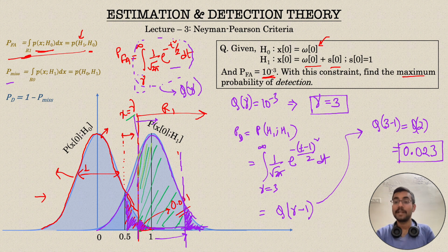So to find an optimal detector, you cannot make probability of false alarm equal to 0. It won't happen, although ideally we would want so. We would need to sacrifice on the quality of the detector by having some tolerance on the probability of false alarm, because without that we won't get a detector in the first place. We would have a very inefficient detector.